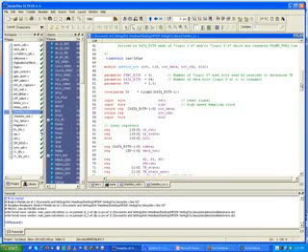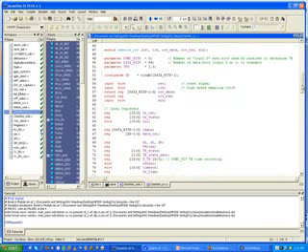So here we have the basic structure for the module called one wire receive. It has some parameters, so I call this a parameterized module, since we can change these parameters from outside the module. Okay, so here I specify the number of sync bits and the number of data bits, my default values. Then I make even some local parameter calculations here, and then I declare my inputs.